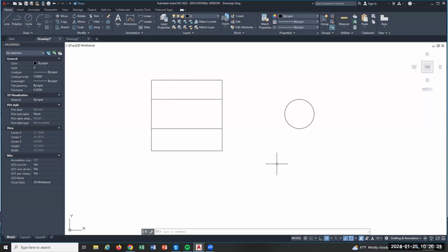This you might want to take a note on because it's not absolutely straightforward. AutoCAD is trying to save some memory. This is a very memory intensive software. So when you save files, those files are big. But if AutoCAD had all the line types in there, that file would be a lot bigger. So AutoCAD doesn't do that. It doesn't load line types until you ask for them.